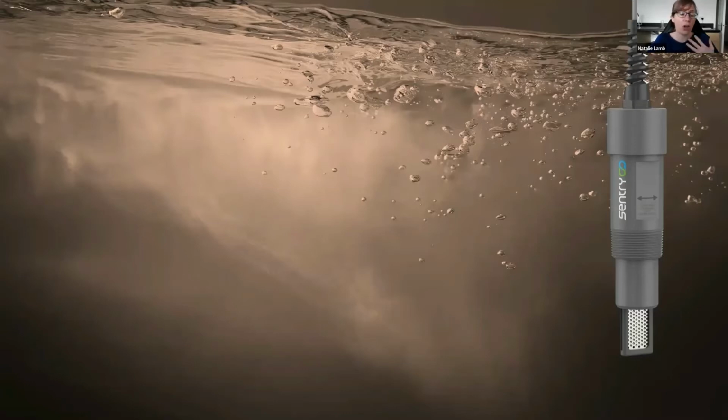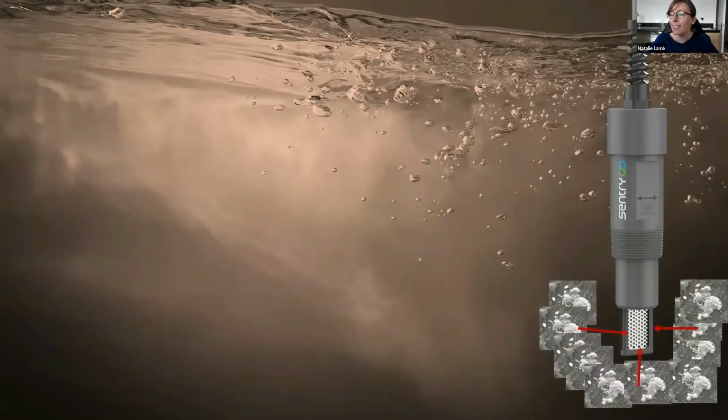For instance, an ammonia probe is going to get growth over time, and you've got to take it out of the water, maintain it and clean it, because it stops working and the signal doesn't work anymore. But this device is actually designed for that biofilm to grow on it. That's the purpose of it. So you're not taking it out of the sewage, not cleaning it, not maintaining it, you're just putting it in and letting all of that biofilm grow. That's exactly what it's designed to do.